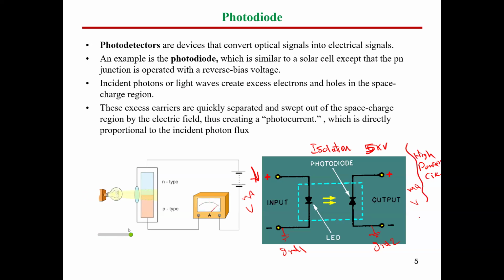So this high power circuit, guys, can be some power electronic switches, and these power electronic switches will have 3 terminals, 1 terminal for the gate and 2 terminals for the power. The gate terminal can be connected to the output here with relatively low voltage, like let's say 15 volt, for instance. But the transistor itself, or the power switch itself, can support maybe like 1700 volt, and the current can reach hundreds of amperes.